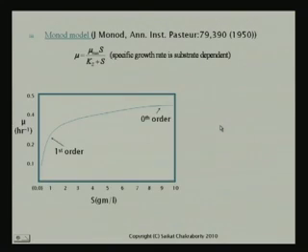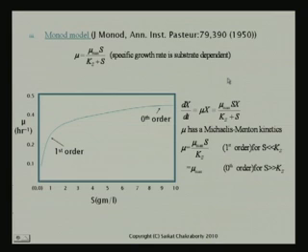The most important model that we talked about, and used several times, just as a recap, is the Monod growth model, which was first derived by J. Monod in 1950. It says that mu, the specific growth rate, equals mu max, the maximum growth rate, times the substrate concentration divided by Ks plus S, S being the substrate concentration and Ks being the growth constant.